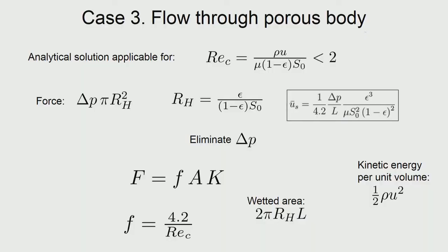That is, friction factor as a function of Re will be sloping downwards as 1 by Re and then becoming flat at very high Reynolds number. So, if this image is there in our mind, then there are many problems that can be solved directly to get the trends. Now, let us see how we have modeled the porous medium flow. Porous medium flow was modeled as a bundle of tubes.